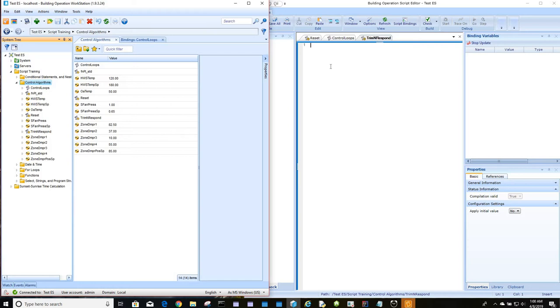So right now, most buildings that don't implement this measure will control the supply air duct pressure to a static 1.5, for example. But a lot of VAVs at this 1.5 inches of water pressure might close all the way down to 5% at minimum flow when there's no thermal load in the space.